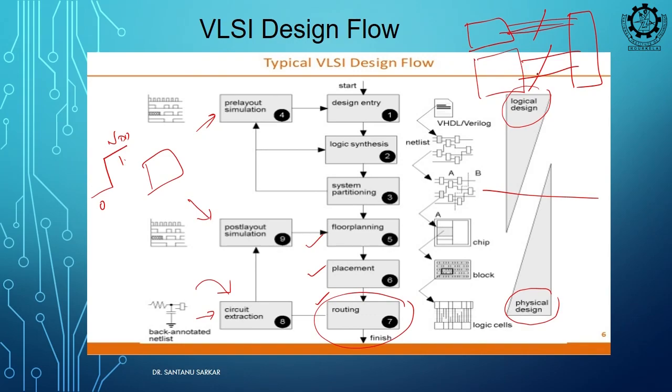You consider that each of these lines will have some parasitic capacitance, so they are going to be charged and discharged fully, 0 to VDD. As much as this data will flip, there will be charging and discharging, right. So all of these buses will have some parasitic loss due to this capacitance.